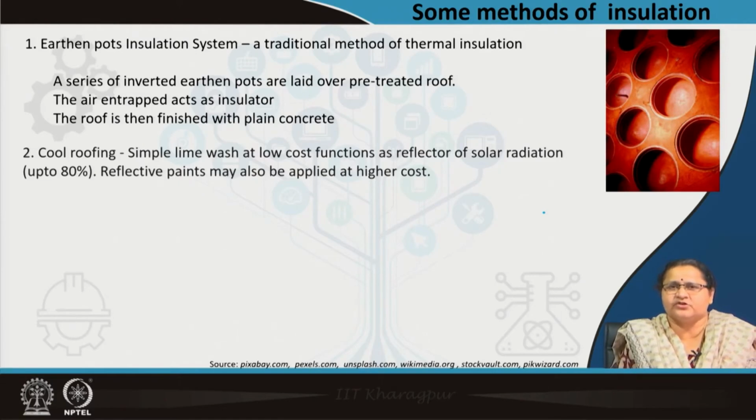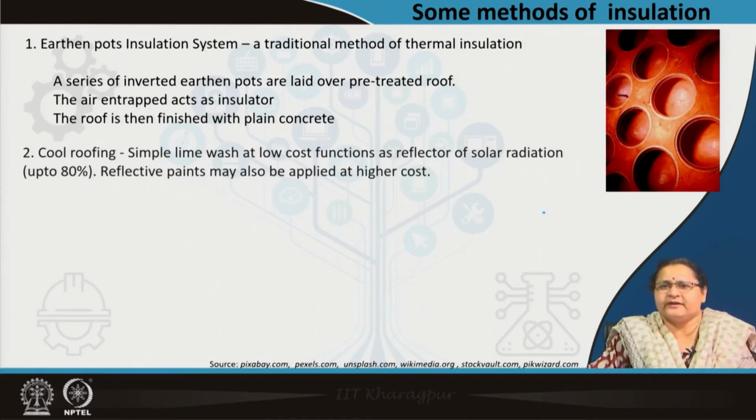The inside got insulated, the solar radiation got reflected. So, we had learned reflective insulation. We are applying the same principle here in a very cost effective way to prevent solar radiation from getting trapped inside the building from the roof.